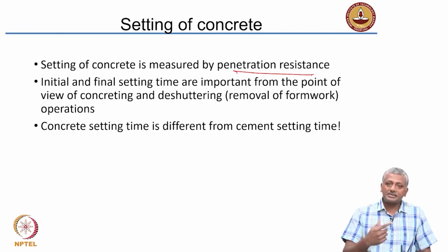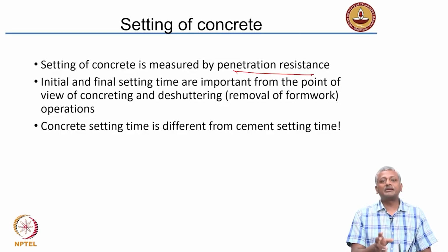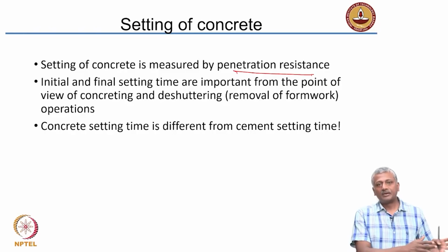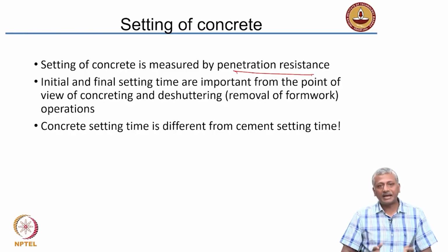Okay, again, just to emphasize once more, concrete setting time may be quite different from cement setting time. This is again an issue because concrete setting is also determined by the cement paste to aggregate ratio. It is also determined by the presence of these mineral and chemical admixtures that we add to the concrete. When we look at cement setting time, we do not add any of those ingredients. Okay, we test cement setting time as it is, whereas for concrete we test it as the concrete mixture has been prepared with all the additives. So, because of that, you need to ensure that you have some sort of an idea about how long it takes for concrete to set.